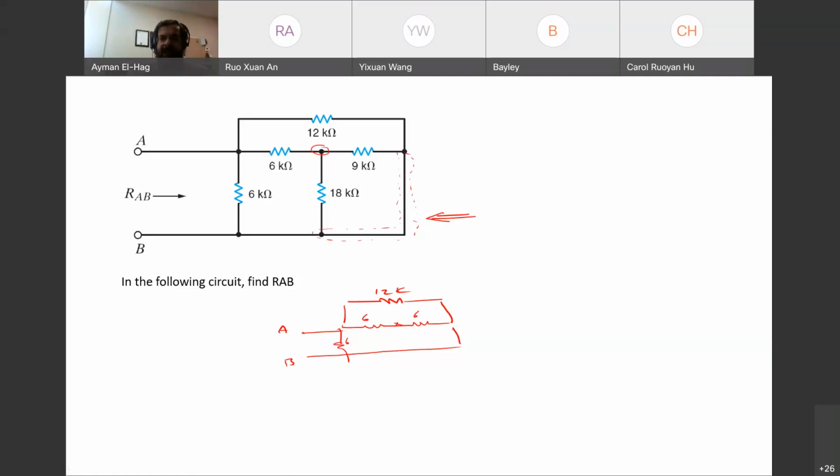Any question here, guys, about circuit reduction? So more than two elements can be in series, right? Like all the 6 ohm. No, the 6 ohm resistors, these two are in series, but this is in parallel with the equivalent.